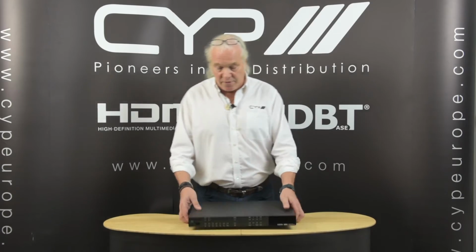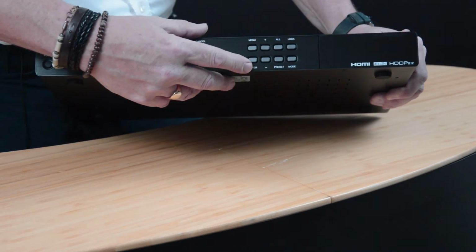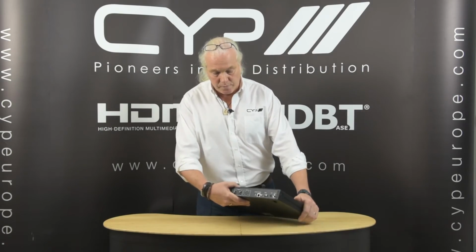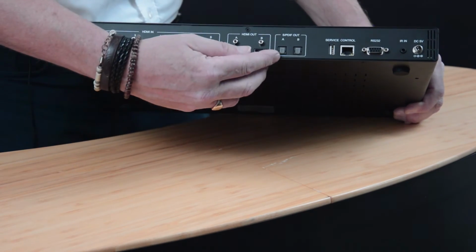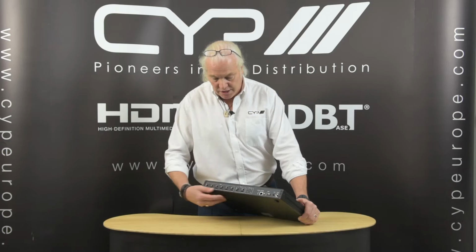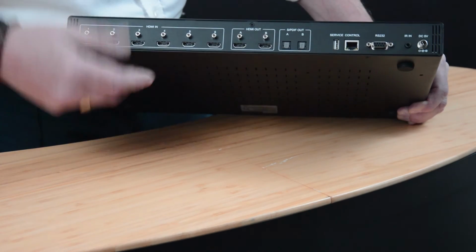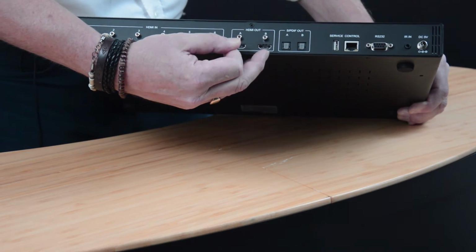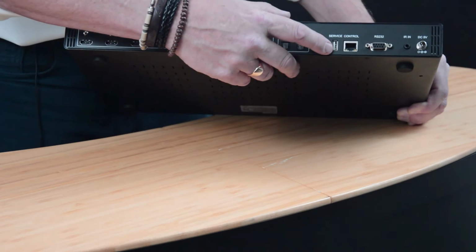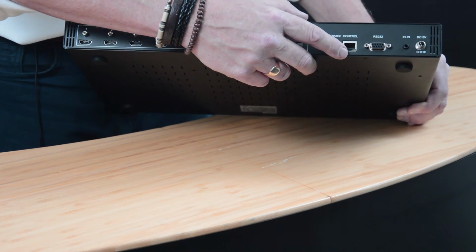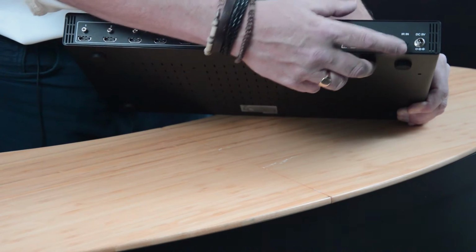So looking at the unit itself, there are hard button keys at the front for selection of sources to outputs and hard keys to access the menu. Now on the back of the unit, we have 6 HDMI inputs for the sources, the 2 HDMI outputs, and each one has its own optical de-embedding output. So in matrix mode, any of the sources can be selected independently to outputs A or B. In switching mode, any of the sources are outputted simultaneously to the 2 HDMI outputs. And remember, in switching mode, you can also view picture-in-picture. There's a service port for firmware updates. There's a LAN port that allows you to access the Telnet commands and all of the web GUI, RS232 for control and the IR input.